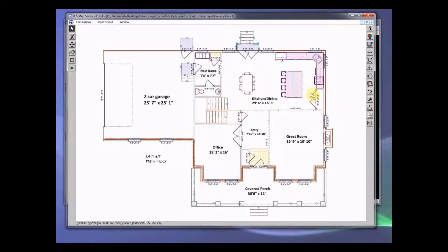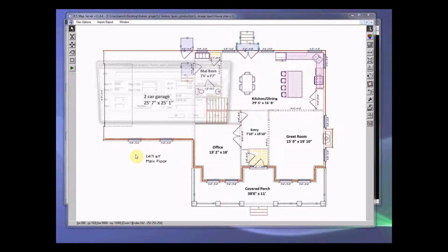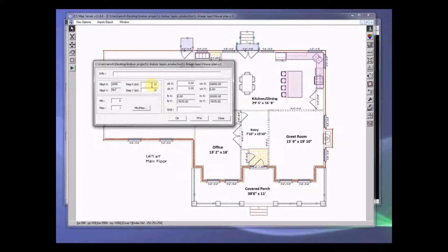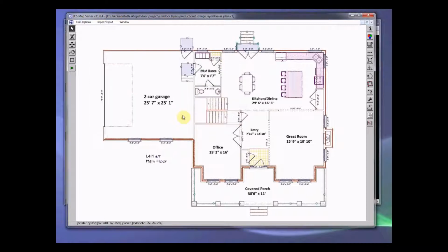There we go, and it looks quite alright. If we now look at the information header, we can see that the step size is 10 meters. However, this is not correct, and the corner coordinates are also something that doesn't make sense. So what we need to do first is, georeferencing of an indoor project does not make sense, so we don't do that. So first we set the grid code to be 1 null, then press OK.